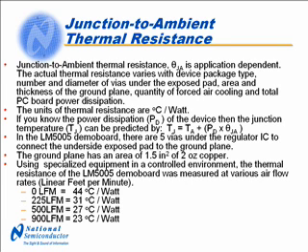For the LM5005 demo board, there are 5 vias underneath the regulator IC to connect the underside exposed pad to the ground plane. The ground plane has an area of 1.5 square inches and is made of 2-ounce copper. For the test data that we took in a controlled environment, we did it at various airflows, referred to as cubic linear feet per minute. So for no airflow, the theta JA measured was 44 degrees C per watt, and that went down to 23 degrees C per watt for 900 LFM of airflow.